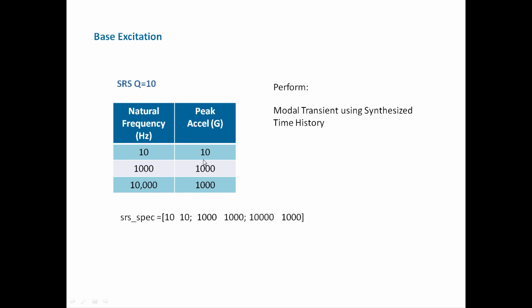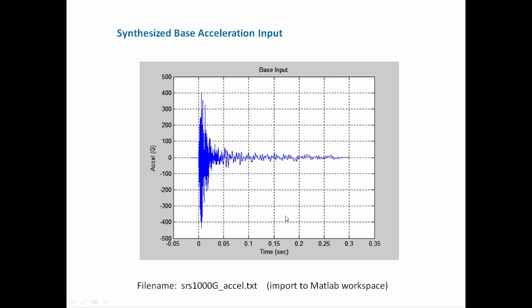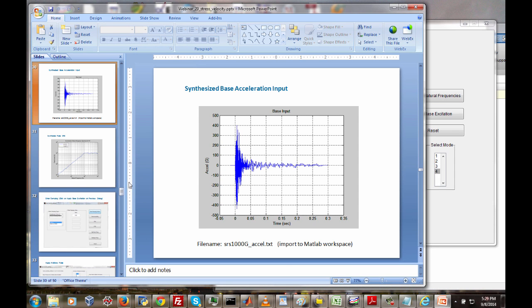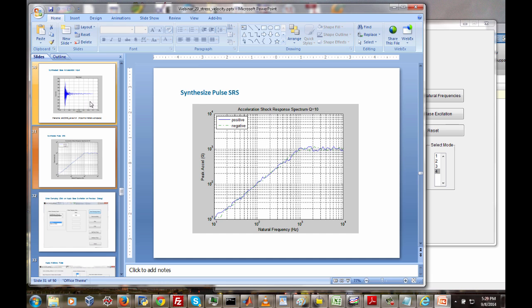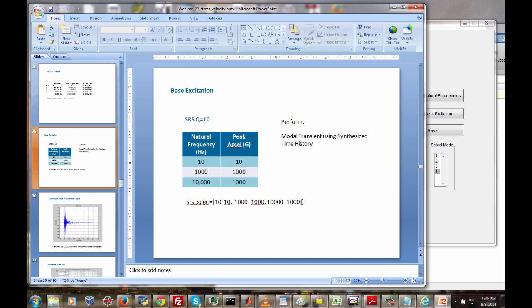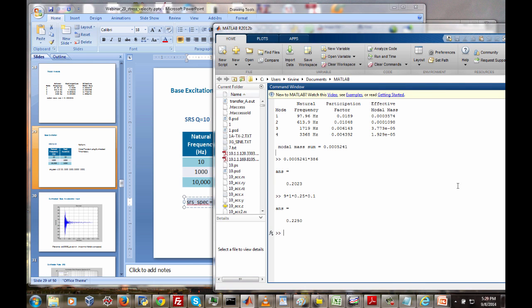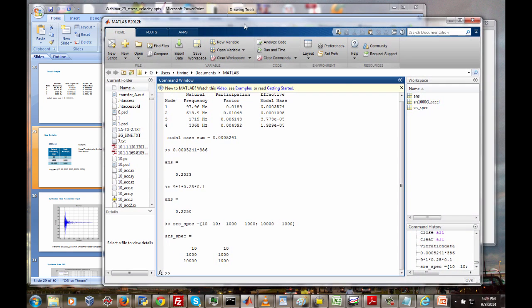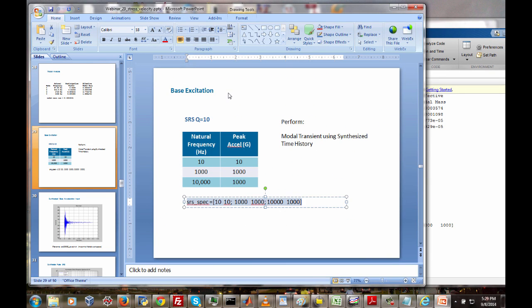This ramp here has a 6 dB per octave slope. So it's a constant velocity ramp. And then I show the breakpoint. This is one way we could get the breakpoints into MATLAB. In fact, let's go ahead. I think we're going to do something with that here shortly. So I'm going to copy and paste this into the MATLAB command window. So now in our MATLAB command window in our workspace, we have this array. These are the specification points. We'll use those a bit later on.